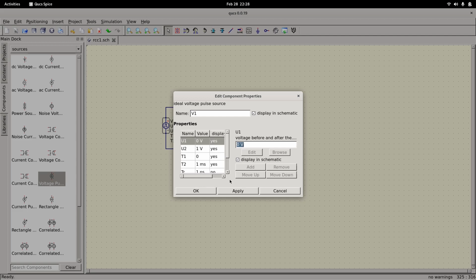So after that there is no point in keeping the signal infinitely long duration. It should stay high at least for 5 time constants. So say our time constant in the circuit is 1 millisecond. We will make it high for 10 millisecond. Then that is equivalent to a step function or step voltage.